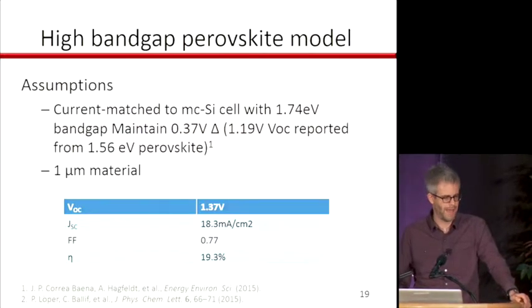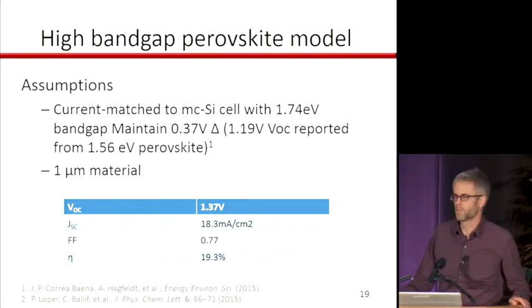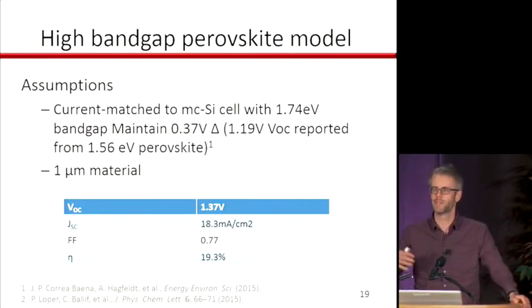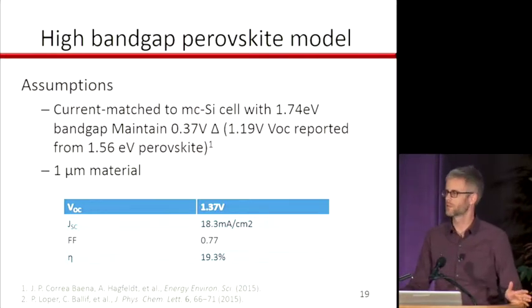You add that to the 19 from the perovskite, and we think 27% is very doable. And then, of course, the theoretical limit is 42%, and you go to numbers in between those ranges when you use higher quality silicon, like single crystal HIT cells, for example.